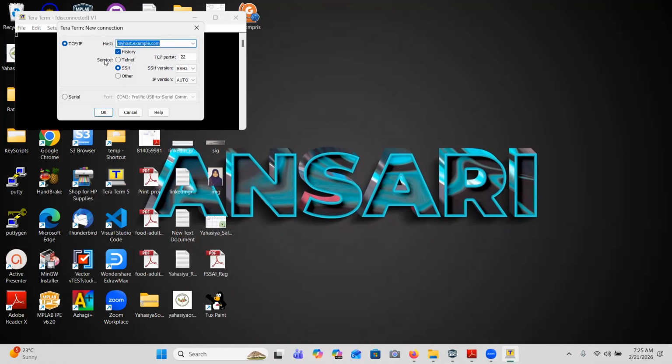Just select that and open it. After opening it, you choose serial. In serial, you can say which port you have connected. Whatever port has a valid serial device will be listed here. As I connected the Prolific cable in COM3, it is listing COM3 here. So I selected that and clicked OK.